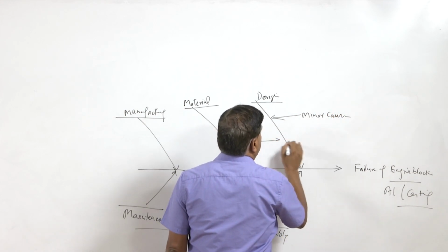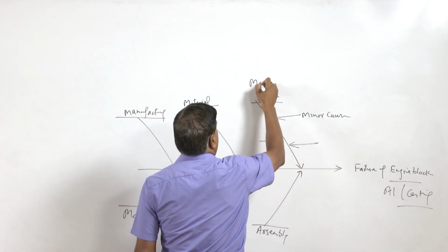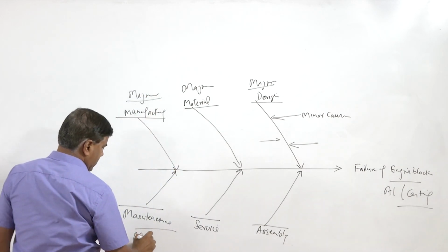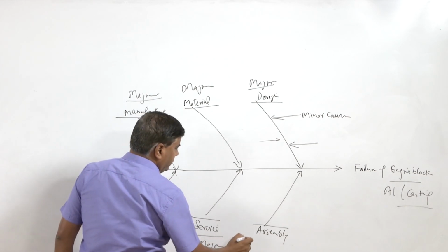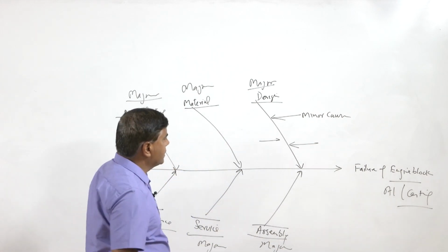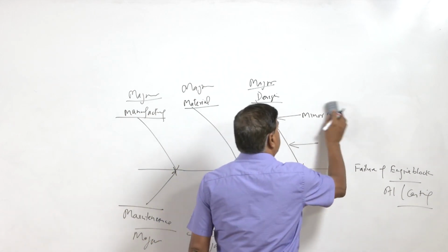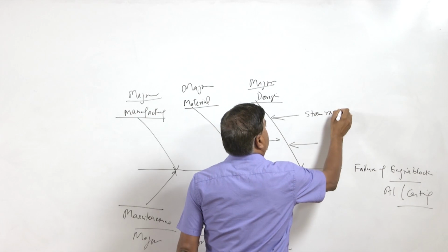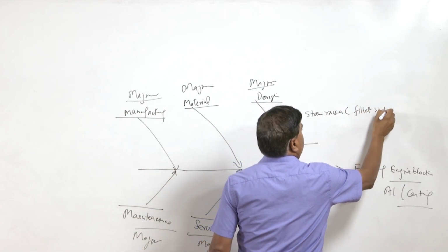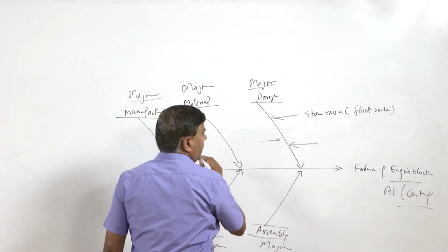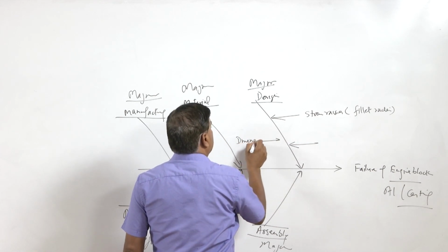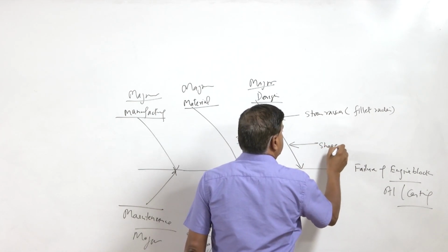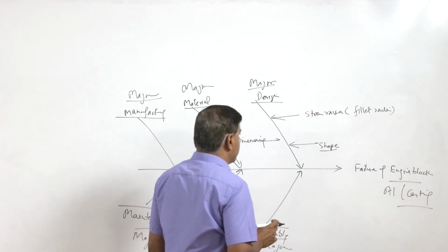like this. So, these minor causes are indicated again by the horizontal line connecting to the major causes. So, all these are the major causes. But the major causes are not actionable. Certainly, we have to find out the finer details on which action can be taken, like the stress raisers. Stress raisers can be addressed by giving proper fillet radius, or by proper dimensioning of the product in light of the service loads, and proper shape, so that the stresses are more uniformly distributed and localization is avoided.